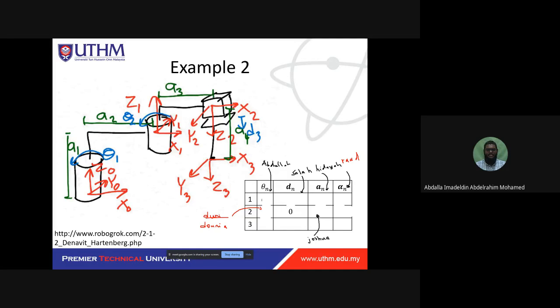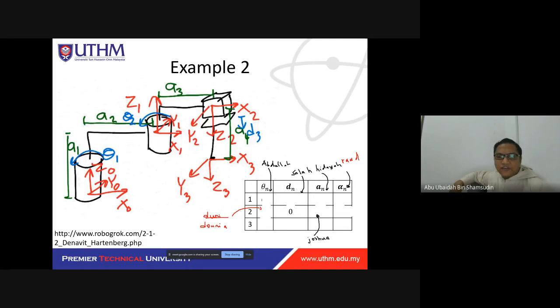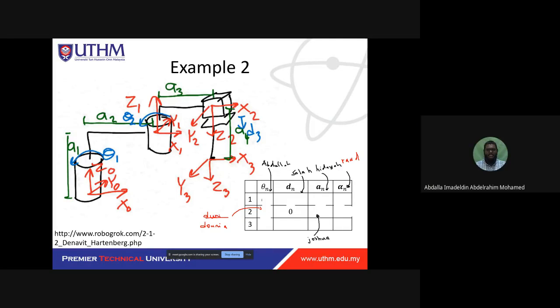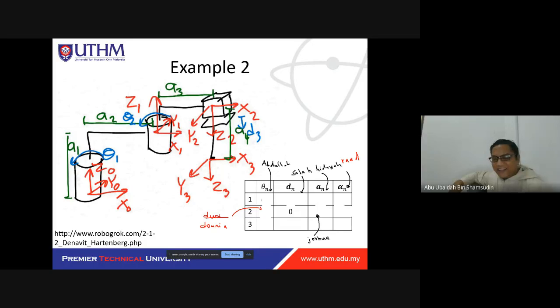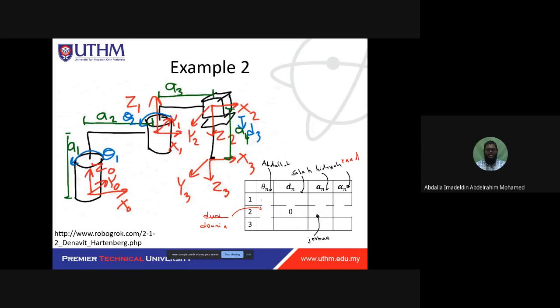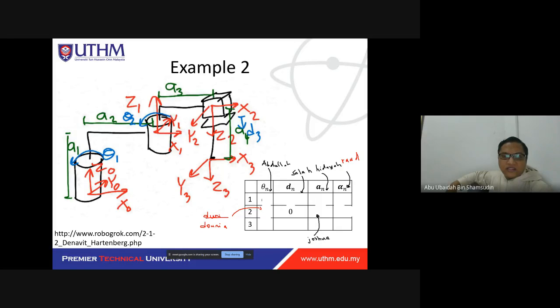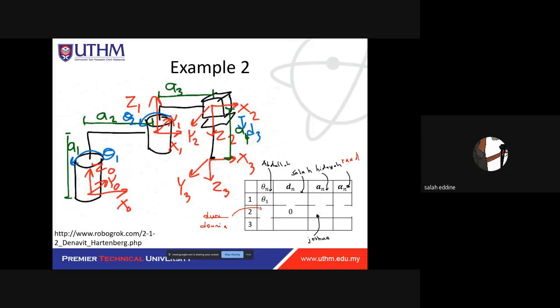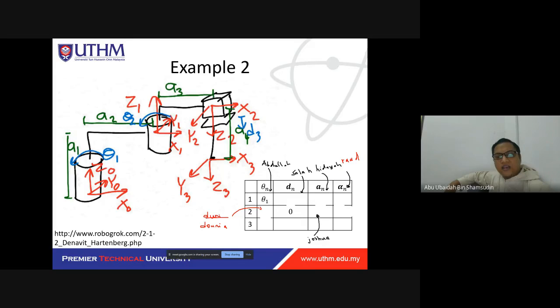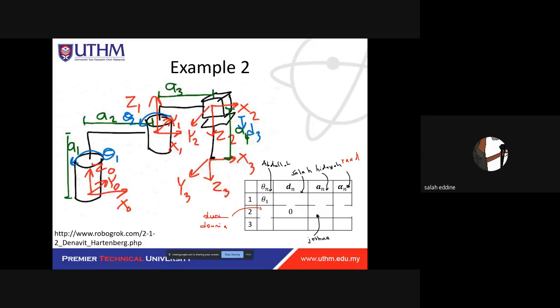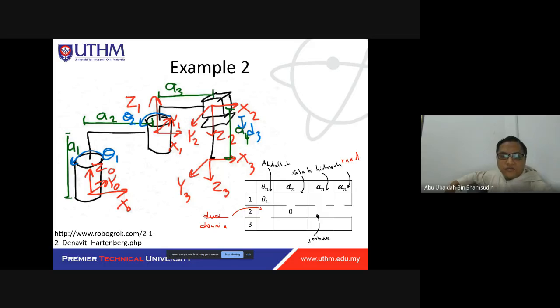I think the first one is easy, I mean, my part. The first one is always theta as a variable, since it is moving, an active joint, isn't it? Yes, because this one is an active rotation joint, so it is theta. You're correct. But some don't have an active rotation, so you need to look at whether this is an active joint or not.